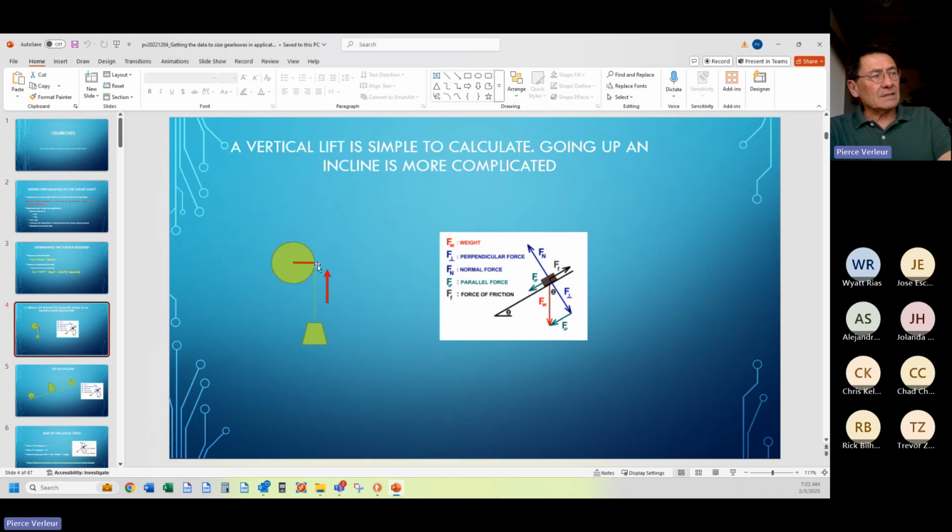Now, we can get crazy and say, okay, sometimes the load is underwater. Well, okay, now we have the resistance of the load to the fluid. If there's a downdraft, well, I've never had an application like that, but theoretically that would put some downforce on the load itself, depending on the profile. And we'd have to calculate the force of the downdraft on the surface area of the load. But the bottom line is, this is very simple. This is the weight times the radius.